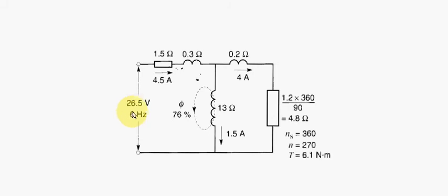So the idea is, if we can boost this value enough to the point where we can achieve 1.9 amps here, well, then we can still maintain constant torque. And that's the whole idea of boost. Now, the way we get this value, okay, we can just physically look at the motor and see how it performs.